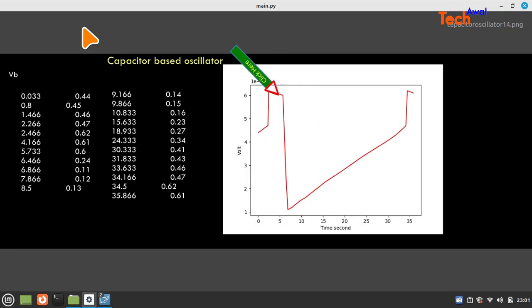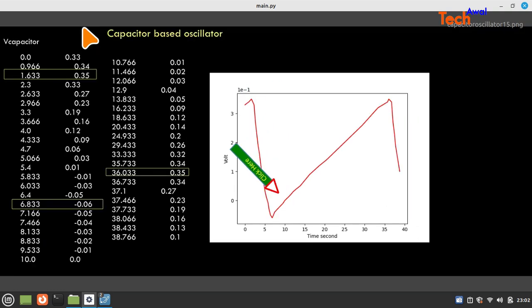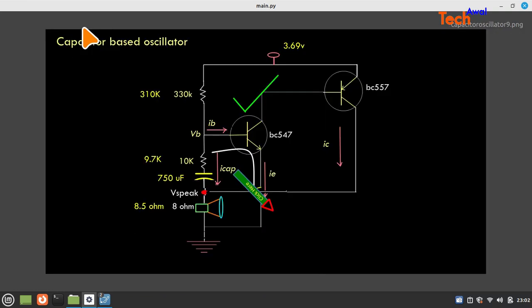It stays at one location and goes down instantly, behaving like a switch. When the capacitor is discharged completely, the transistor becomes switched off. Then this path to the right side has infinite resistance and the capacitor starts charging again. So this keeps happening.